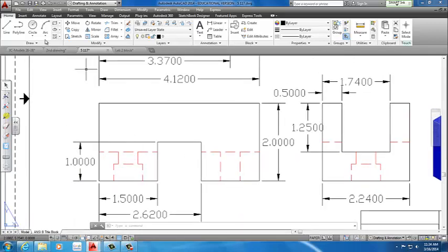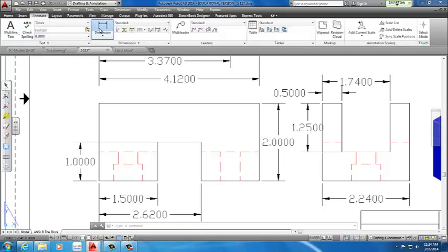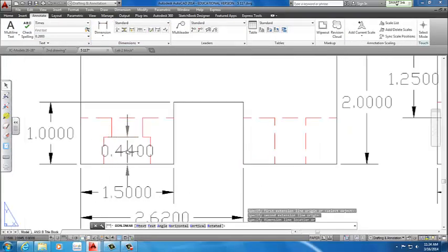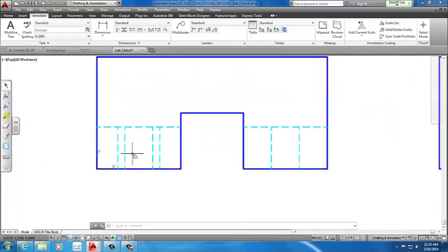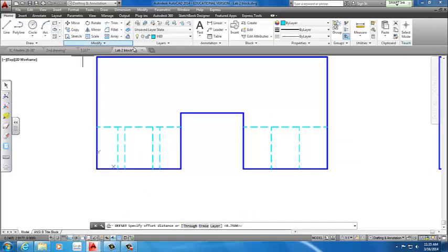The command bar will ask you to select the object to sweep. This is the object that we're going to be using to sweep, which is going to be just our circle. Now to do that part, we will offset that bottom line. We go to the offset command, type in 0.44, because we do not want to select any more objects. So we click enter, 0.44, and enter.